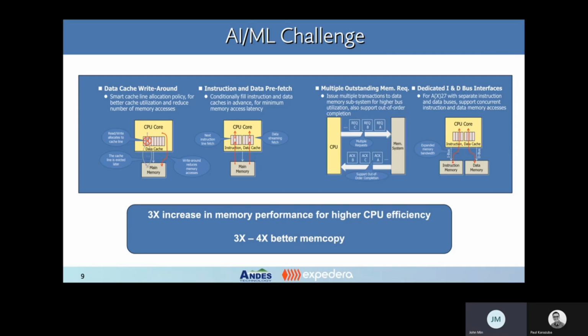So we're on and off the bus as quickly as possible, but we'll bring in as much as optimally necessary. Third thing we do is outstanding memory requests. In CPU systems, SoCs, there are slower memories, fast memories, slow peripherals, and fast peripherals. Well, you don't want access to a fast peripheral to be slowed down by needing to complete the slow accesses. So we have out of order memory reads and writes. This accelerates overall system performance and makes all the peripherals perform at the optimal level.